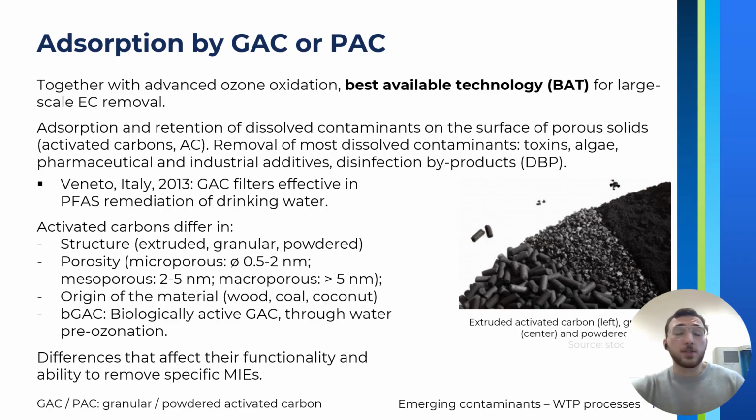Among the advanced treatment processes for emerging contaminants that we have been talking about, activated carbon is among the best available technologies for emerging contaminants removal. Adsorption by activated carbon is a type of mechanical process to be included into filtration regimes. Dissolved contaminants are actively removed from the water matrix by adsorption and retention on the surface of highly porous solid materials, in this case activated carbons.